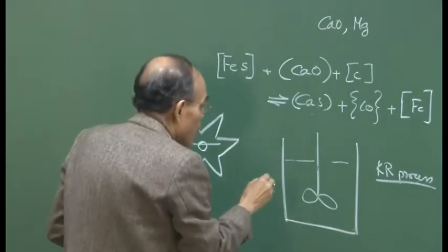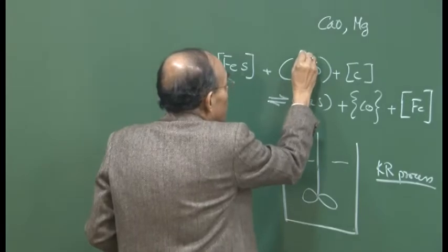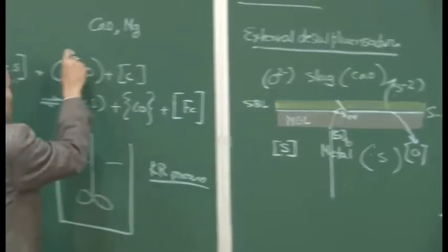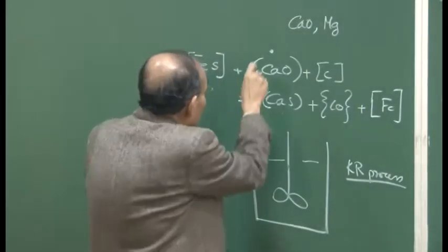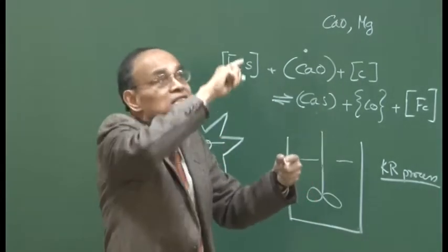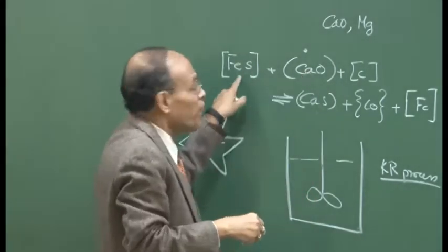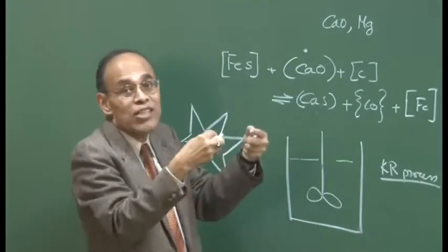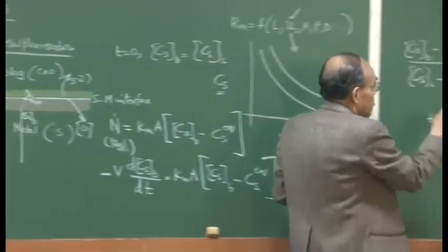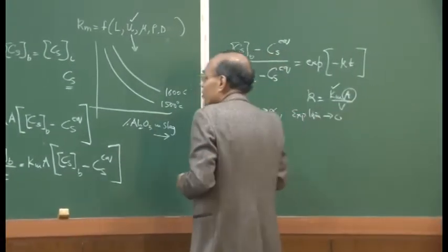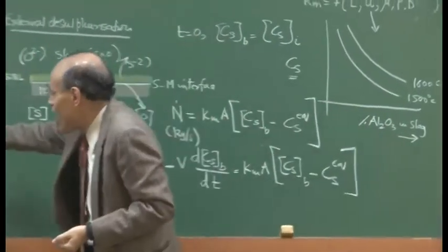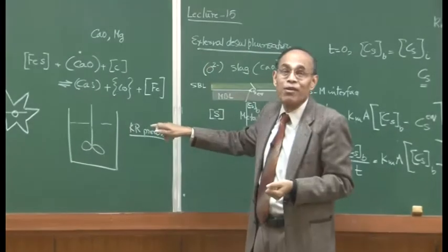Okay. So, we have calcium oxide, it is now available. I have drawn the slag metal interface in an exaggerated way here, but if a large number of droplets of calcium oxide particles are injected, that indicates that an enormous surface area is created where calcium oxide and FeS will come in contact with each other, and that is going to expedite the slag metal reactions. So, therefore, to get a very large interfacial area, this A is the reaction interface area. This is not the wall area of the vessel or the planar slag metal interfacial area.